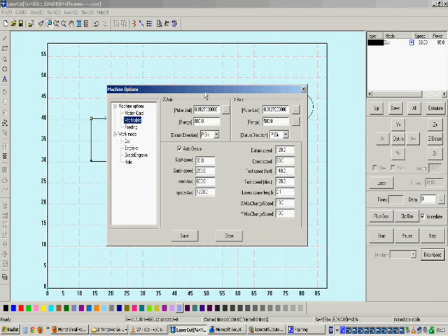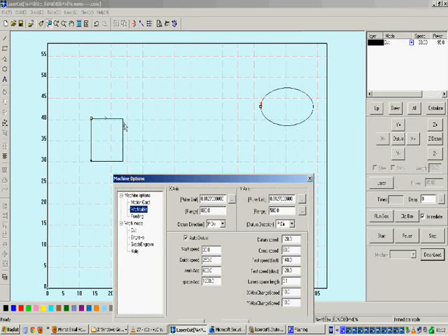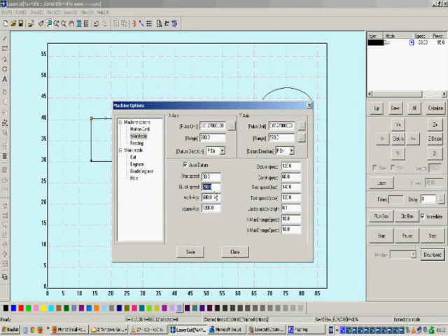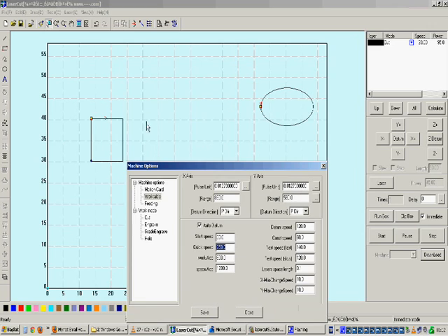So increasing the quick speed decreases the time lost between different cutting operations, if they are far from each other. But if they are close to each other, this will not give you shorter cutting times, because the time lost between them will be too small.